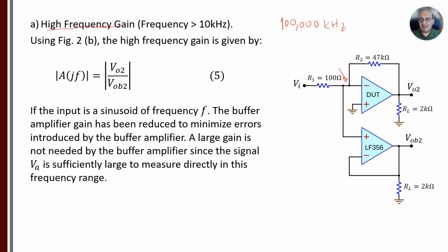So what we can expect here is the output sinusoidal, V out 2, divided by 10, and could be small, well, no longer that small, but we have the help of the bottom amplifier with the one difference with respect to the previous slide. We have it configured as a unity gain. Why is that? Well, if you put the oscilloscope probe here, you might be disturbing the experiment. Having the buffer on the bottom gives you an output which is equal in magnitude, but we are not touching the node under test. And the idea is then to confirm 2 points, right?